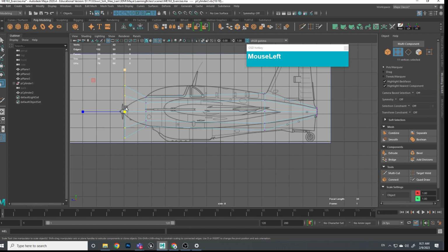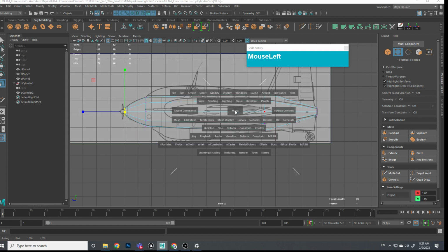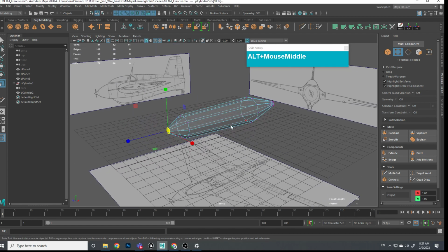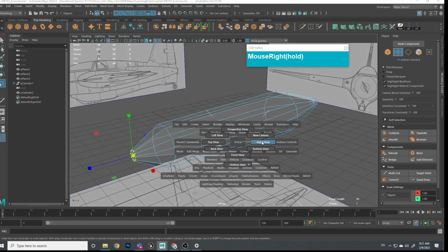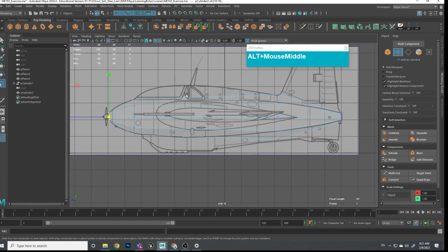Then finally, the last row. The last row you need to select by vertices. Going to vertices, then scale it down until you match here. All right, so now we have this shape. Very basic like that. But you notice that the center part should be thicker, right? So we go back to our right view. We need to insert one more edge loop at the thickest part of the model, which is right about here.